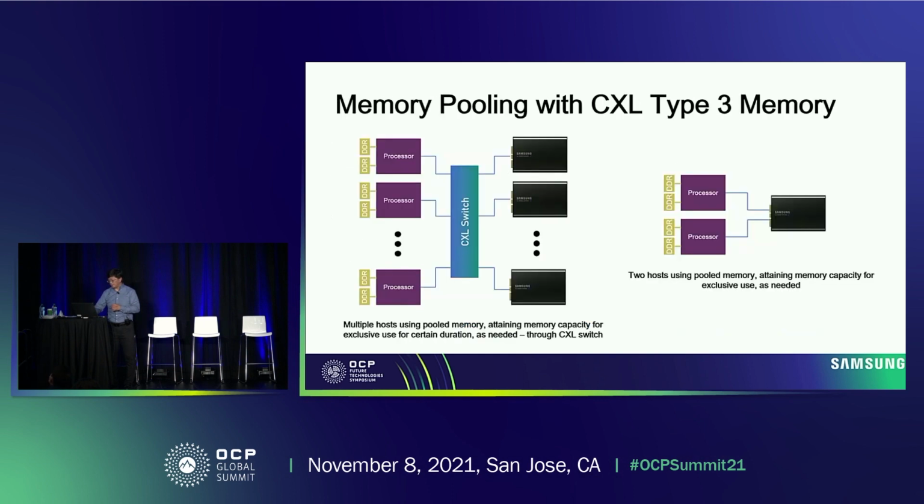Obviously memory pooling is heavily on everybody's mind, and we're collaborating with the industry to bring up these devices to explore direct attach CXL memory, as well as use cases perhaps through a switch. In the case that we don't have a switch, we're looking at something with, for example, dual port, where the device can be configured with 2 ports to be connected to 2 different hosts, and you can pool or share the capacity with the 2 hosts without an additional switch needed.